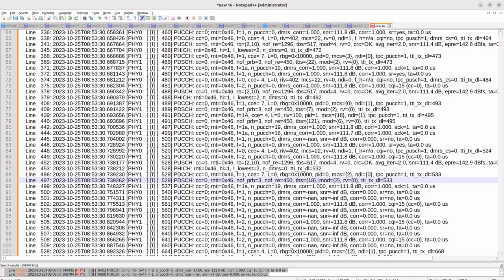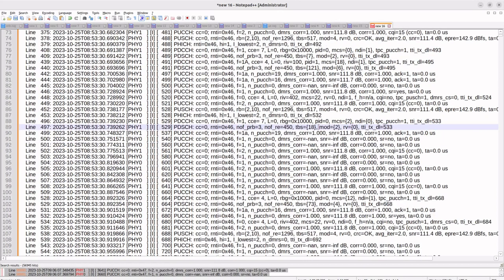If it is uplink DCI, it is related to PUSCH, where the UE in the next transmission opportunity, in that particular scheduling interval, can send that particular data in the uplink. If it is PUCCH, then the UE is carrying the CQI, PMI, RI, the rank indicator, and SR, right? These are all the different information that the UE carries in the PUCCH. Those things I have discussed in more detail in the physical layer discussion, so you can check the details in that physical layer course.